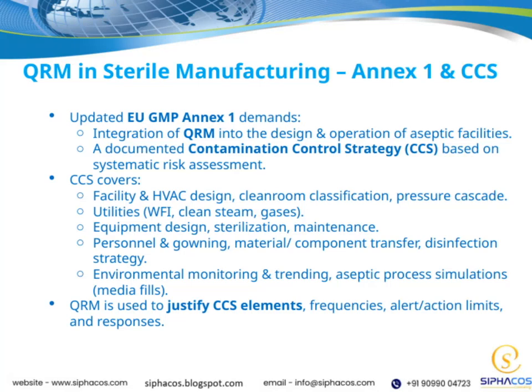Now, let's look at the updated EU GMP Annex 1 demands regarding QRM, or Quality Risk Management. One of the key points is that QRM must be integrated into both the design and operation of aseptic facilities. This means that risk management isn't just an afterthought. It's embedded throughout the entire life cycle of the facility. A crucial aspect is developing a documented contamination control strategy, or CCS, which is based on systematic risk assessments. This strategy acts as a roadmap, guiding how we control contamination risks effectively.